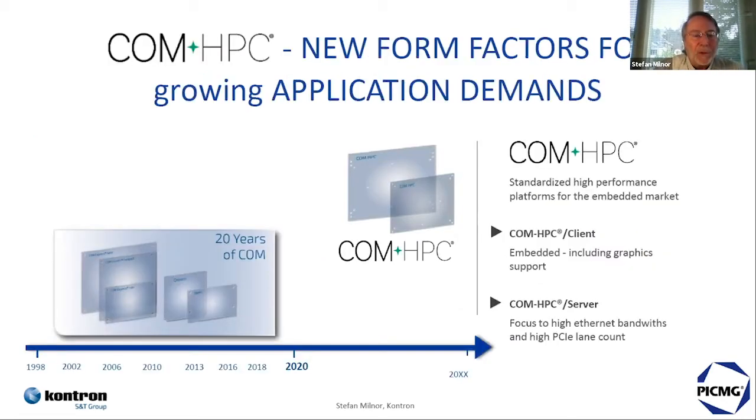So COM-HPC. Kontron's been in the modules business for at least 20 years, starting with ETX and then moving on to COM Express and now to COM-HPC. COM-HPC is meant to augment COM Express, not replace it. It kind of starts where COM Express leaves off. There are two pinout types on COM-HPC. There's a client pinout type, which includes graphics interfaces and a healthy dose of PCI Express. It's comparable to COM Express Type 6,